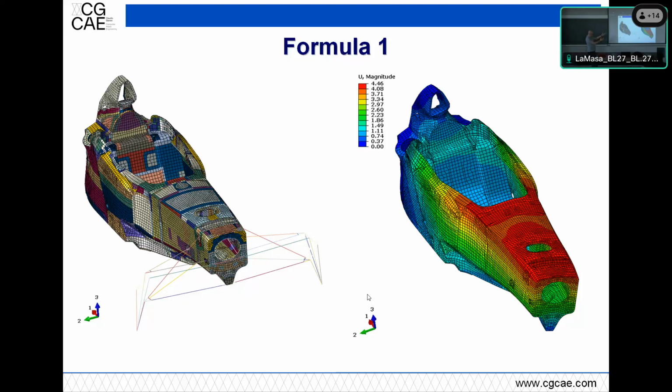It's made from composites, carbon mainly. And the difficulty here was that there was still the zone method, which was used to prepare the properties of each of these parts. This means that you have to manually build up your sequence of lamination with the laminate for every one of these. And maybe the first time it's easy in the sense that you know exactly what you want.